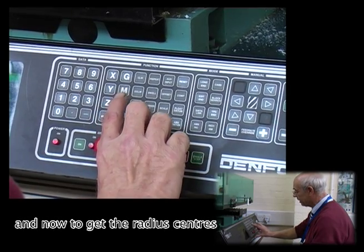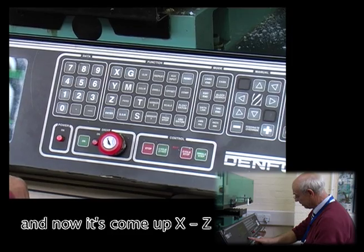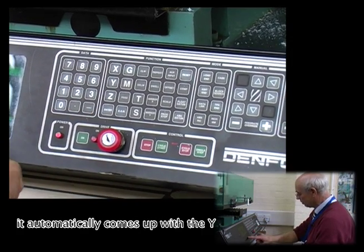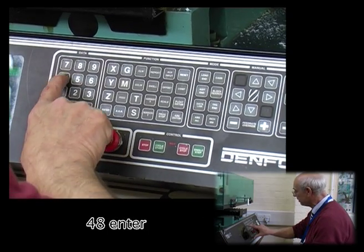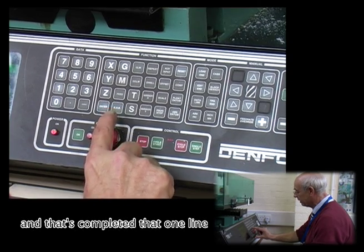Now to get the radius centres, that's the clockwise curve. Now it's come up XC, so I can put the centres in there, 52, enter. It automatically comes up with the Y, 48, enter. That's completed that one line, end of block.